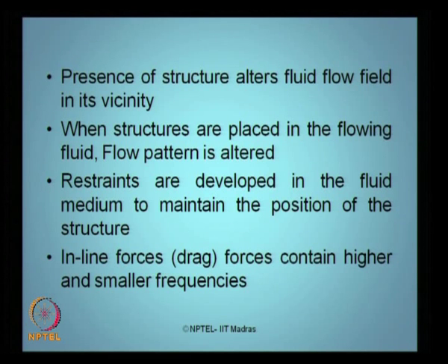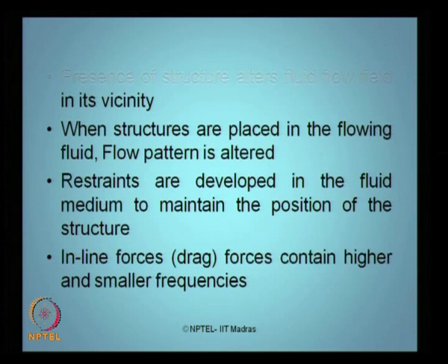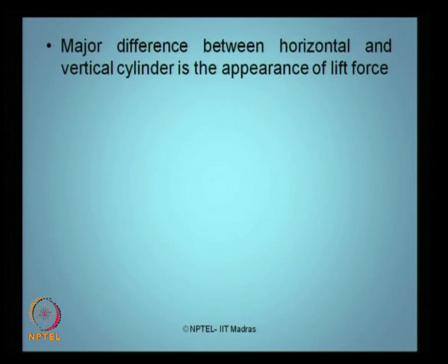So inline forces, what we address as drag forces, contain both higher and lower frequencies depending upon the Reynolds number and the corresponding Stokes number. The major difference actually comes in the lift force in its appearance between the horizontal and vertical cylinder. Where does it occur actually?